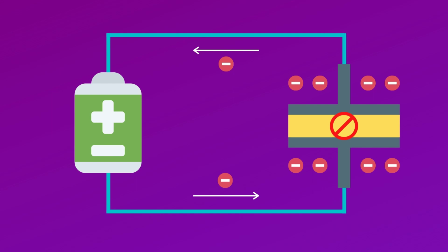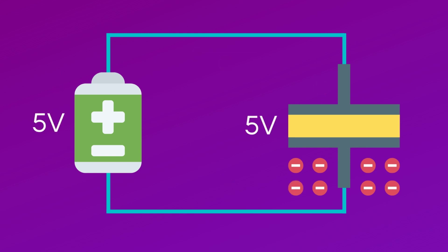it. So what happens? Electrons will flow from the voltage source to the negative plate, increasing the negative charge at that plate, while electrons will leave the positive plate, isolated by the dielectric, decreasing the amount of negative charge at that plate, causing the plate to become more positive. This will happen until there is a potential difference that equals the value of the voltage source. In other words, through this process, the capacitor will charge to almost the same voltage value as the voltage source.